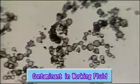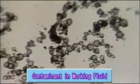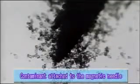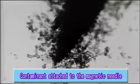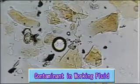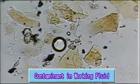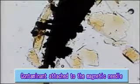This is a contaminant found in the hydraulic fluid of a die casting machine. This too is in the form of fine jelly. Similarly, this contaminant is also drawn to our magnetized needle. With this large injection machine, the contaminant, whose hydraulic fluid additive has changed, is also drawn to the magnetized needle along with other contaminants.